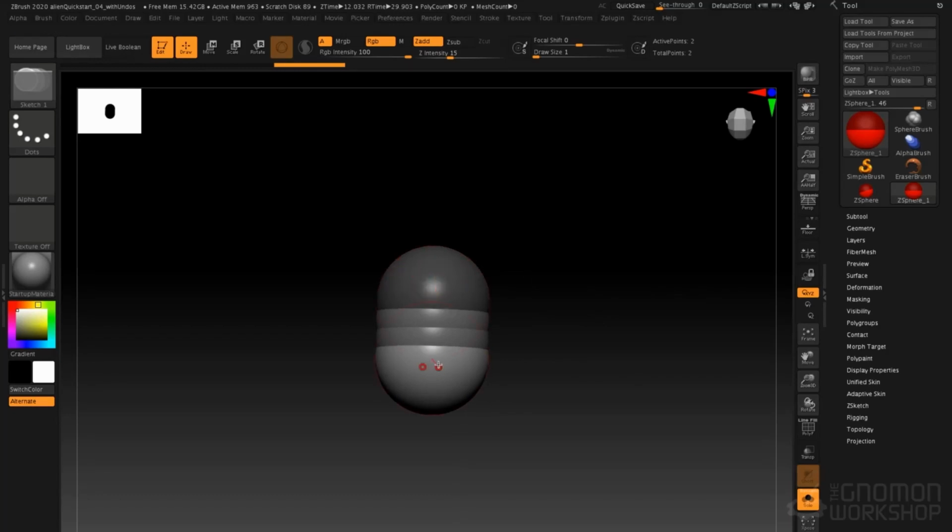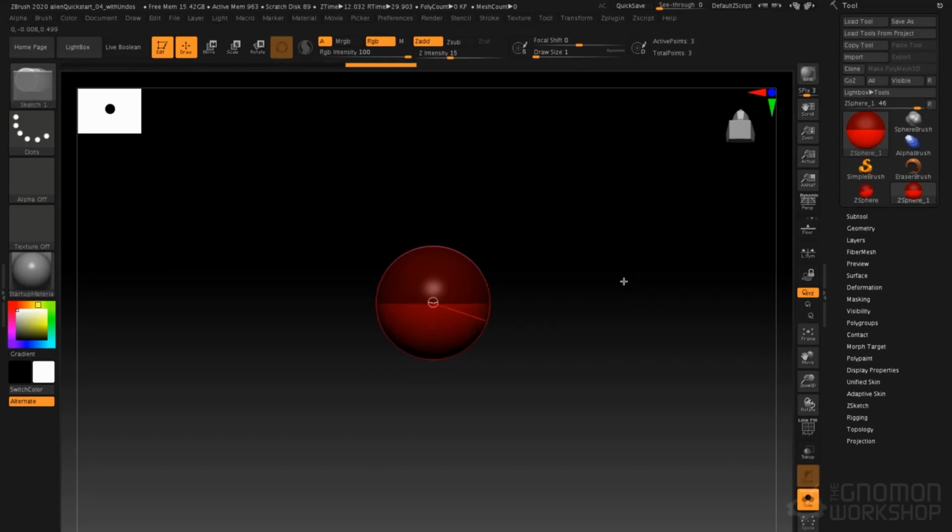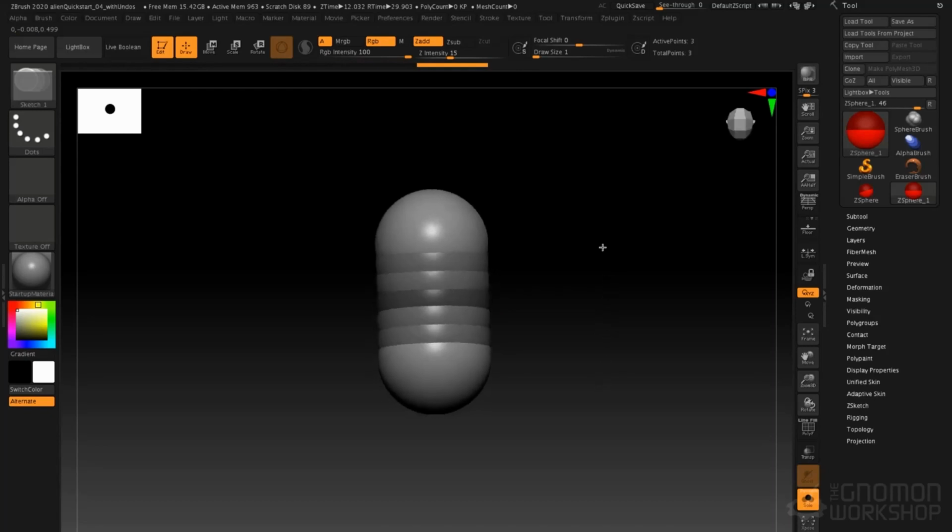Now we can see you've got your root sphere, and then we have a child sphere coming out from the bottom. Now the root sphere has to have a sphere on either side to be a solid mesh, so let's rotate to the other side and do the same thing here. Bring the 2 green dots together, click and drag, press and hold the Shift key, let go of the cursor, let go of Shift, and double-click off the model. And that creates something that looks like this. We have the root sphere in the center and a child sphere on either side.